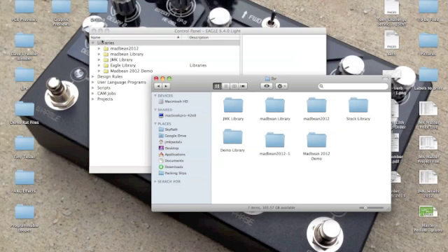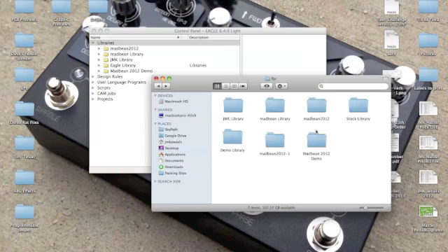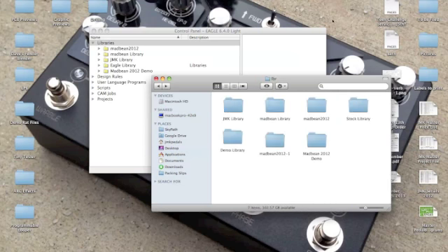This is very handy because you may find that you're not using a lot of the parts in, say, the Gus Markov, the MadBean, the whatever stock library. If you're not using parts, get rid of them and create your own. You don't need to use this library and this library if you're trying to get parts out of both of them. Create your own library and then just copy in the parts that you're using.